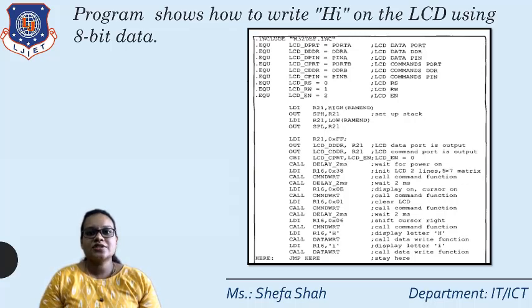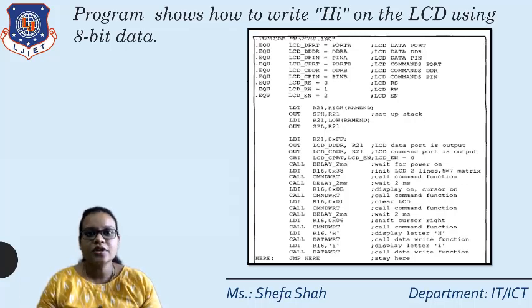Now, the second step is that we need to send the commands to the LCD. Here different commands, that is 0x38, 0x0E, 0x01, and 0x06, are given as commands. These are the 4 commands from the command table which we have seen. 0x38 means the LCD will receive or transfer 8-bit data. Then 0x0E means display on, cursor blinking, so data can be accepted. Then 0x01 is clear display screen, and 0x06 means the cursor will shift to the right and the writing will start from the left side.